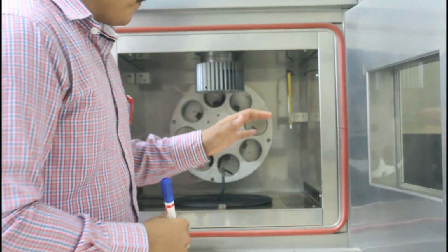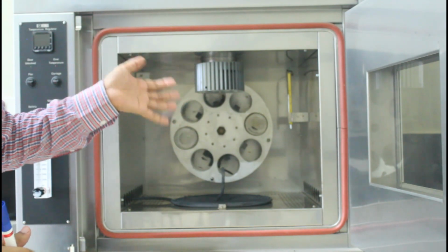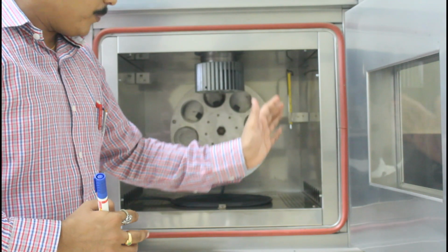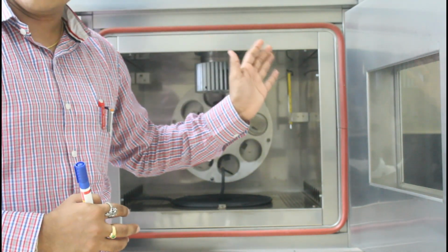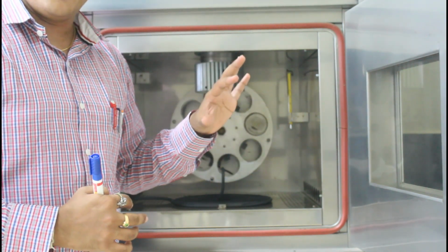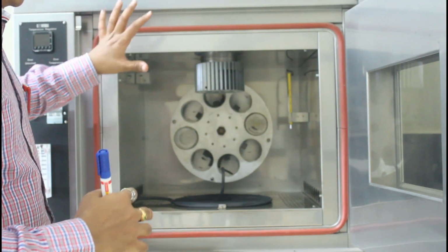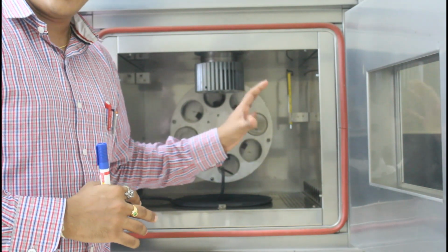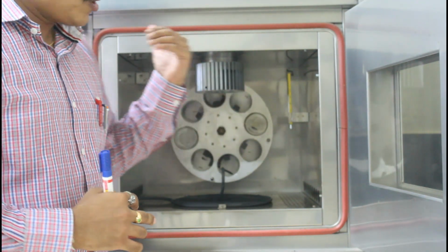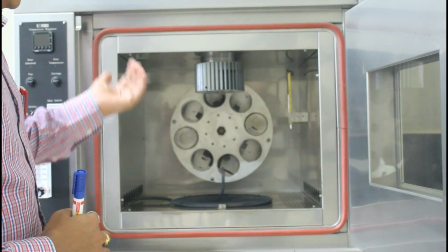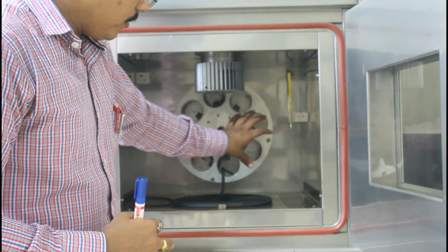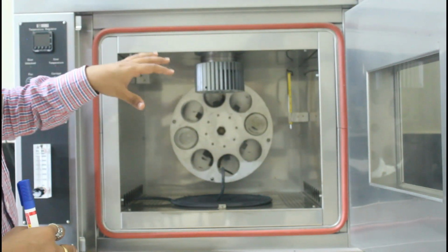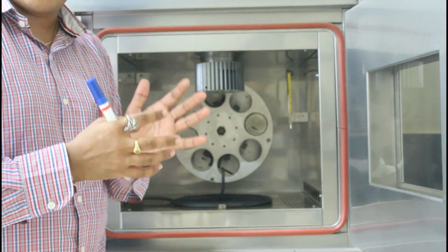Now once you do this, before keeping the bottles, you need to preheat the oven. You will preheat the oven to a temperature of 163 degrees, at least for 4 hours. So why do we do that? To ensure that the whole system is set to 163 degrees Celsius at least 4 hours before testing. So after setting the oven, you will keep the bitumen in the RTFO bottles and allow it to condition for 85 minutes. In the 85 minutes, what happens basically?